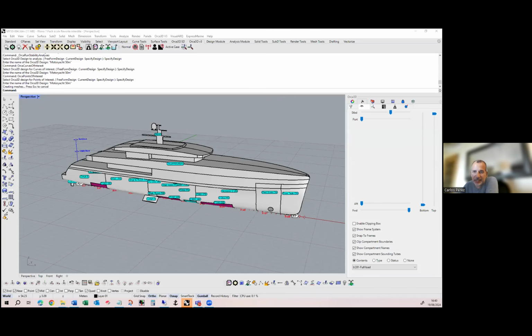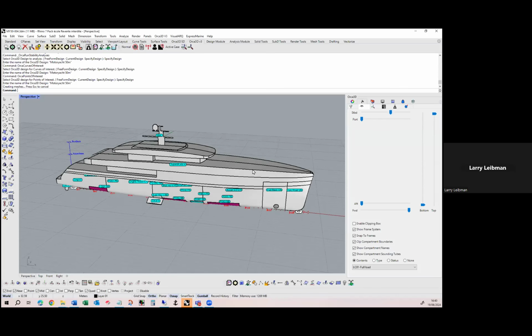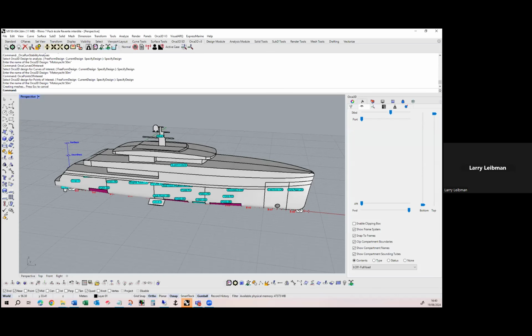Just while Stéphane shares his screen, maybe one question you could answer now, Larry, from Paris Sagand. How is the shell thickness incorporated into the model? Good question. Currently, we don't. You would have to, and we've had people do this, actually model it. We've had people do an offset, a small offset to account for shell thickness, and have it be its own component.